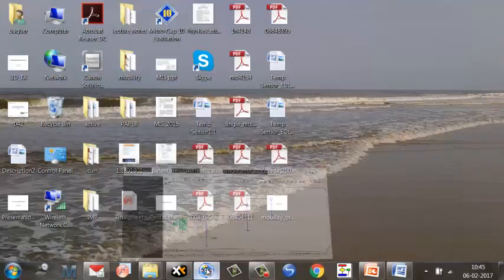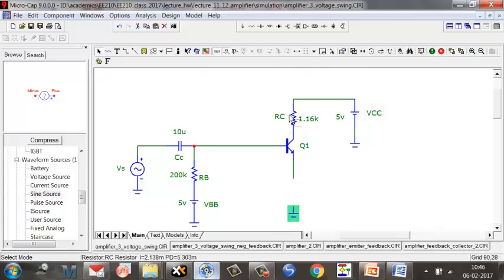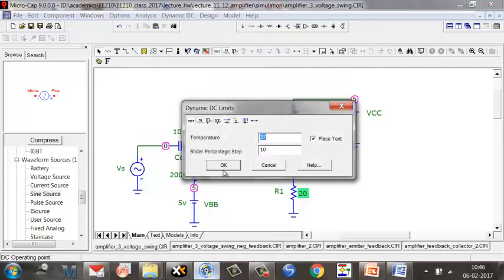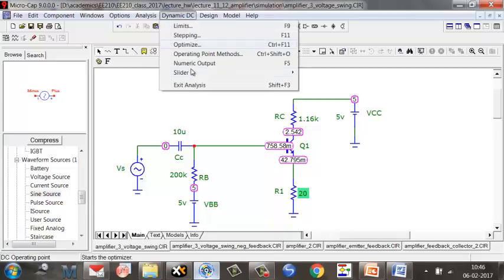Okay, let's see how much we sacrifice. All right, let's go back to our simulation. Here, 2.52. So let's add a resistor. Let's put 20 ohm. All right, 20 ohm resistor. It does not do much to the biasing. It's still 2.54. Earlier also it was biased in the middle. With the 20 ohm resistor it is still biased in the middle, 2.5. So nothing really changes here.